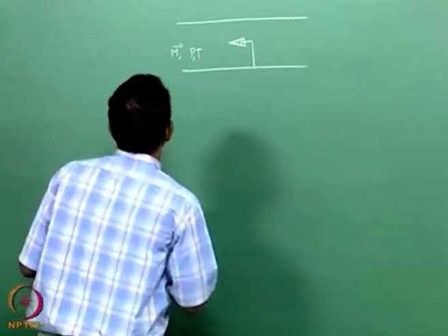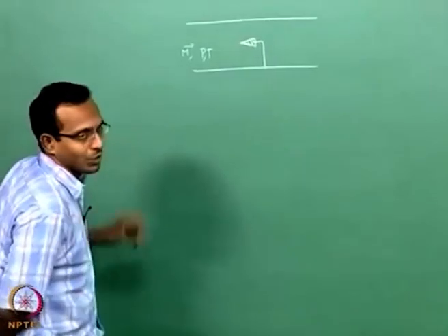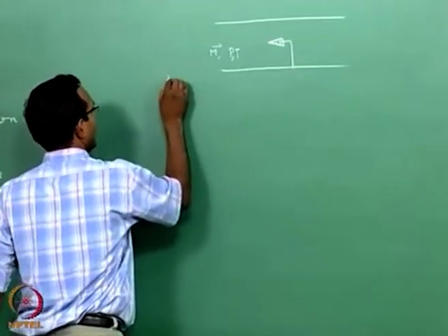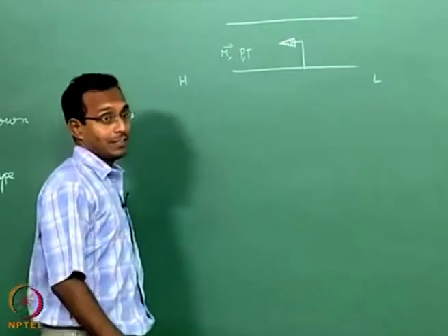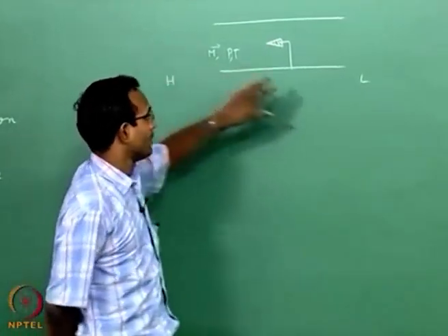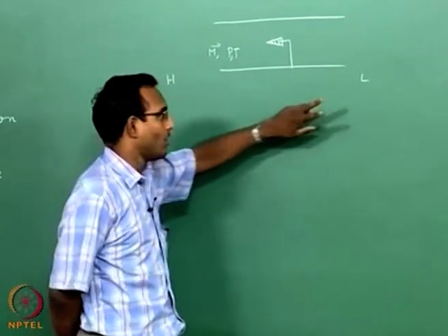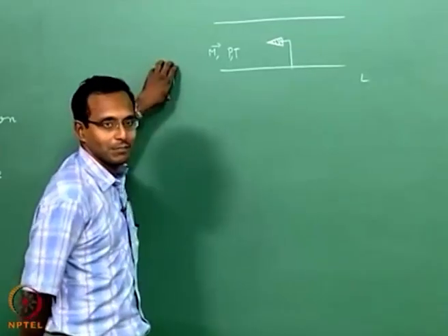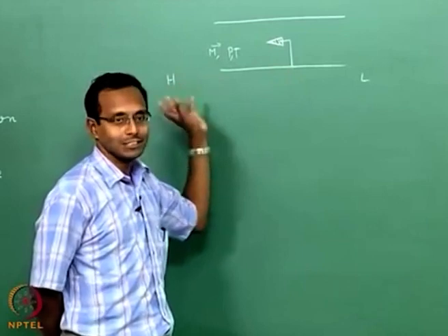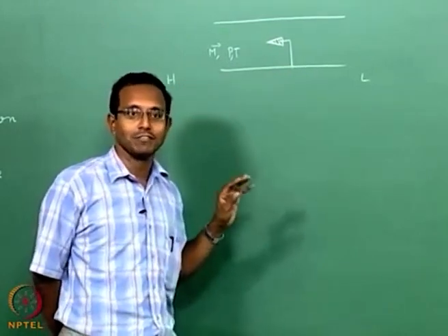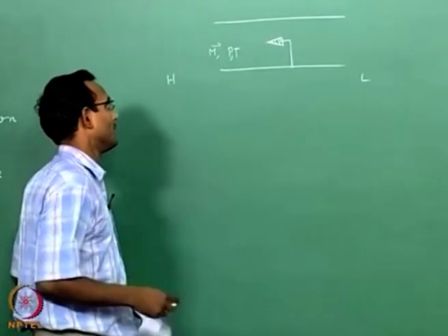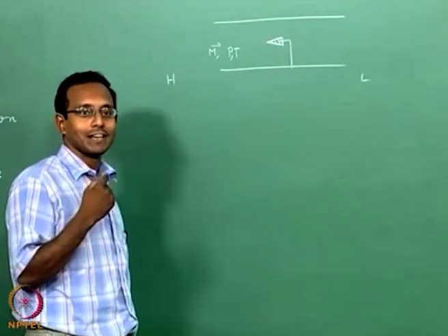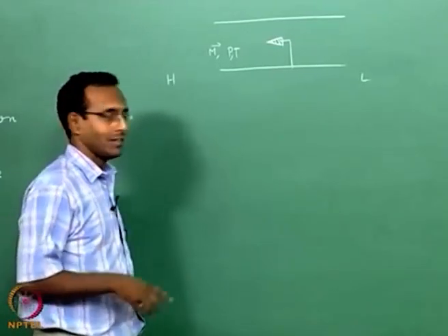Okay. So, the way I am going to think about giving a pressure ratio across this is, basically, I need to have high pressure here and low pressure here. I can either keep this open to atmosphere and make this extremely low pressure, or keep the exit as atmospheric pressure and make this pressure extremely high compared to that. All that matters is just I need to provide very high pressure difference. Delta P needed for this should be provided. That is not enough. I need to have the particular area ratio such that for that mass flow rate it can achieve the correct Mach number. Okay. These are the requirements.